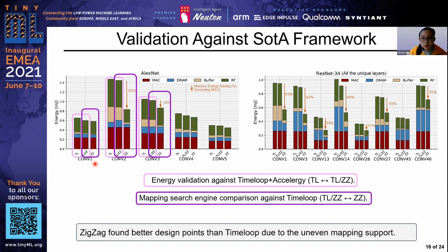Yeah, so we took into account the different operands, like input, weight or output stationarity, when we do the temporal mapping search. We can generate all the stationarity scenarios, compare which stationarity is optimal, and take that one as the temporal mapping. Yeah, excellent. Thank you.